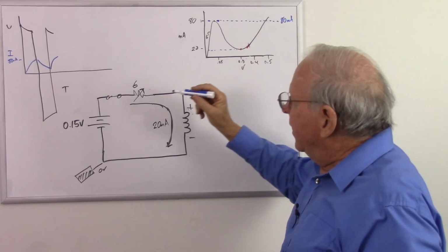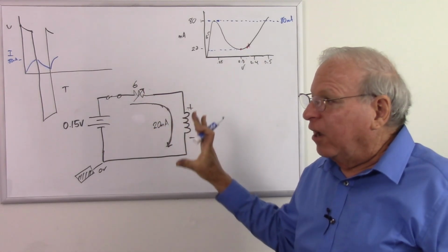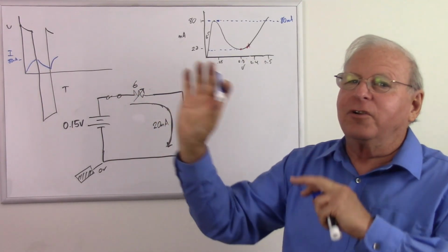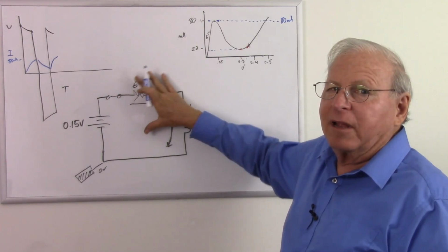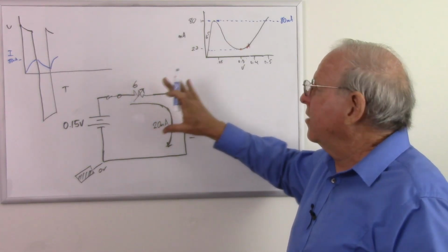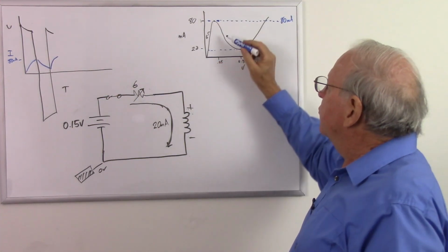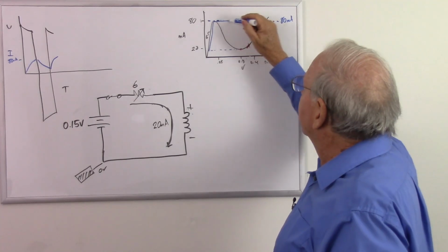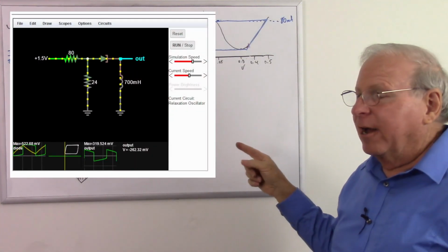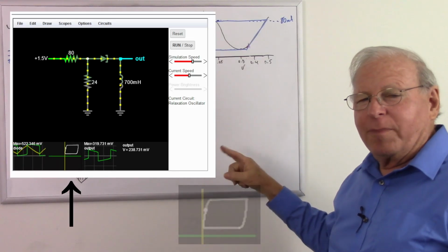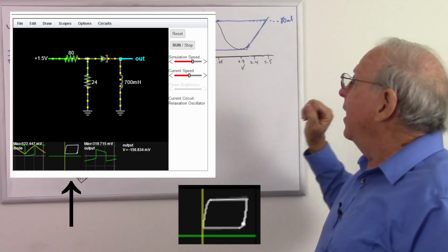And so what we find is that as this tunnel diode keeps adjusting its resistance, just following all these principles we've been learning for all this time, it has to keep changing its impedance from about 6 ohms to about 600 ohms, then relaxes that, allowing this curve to happen. Then it has to jump back down to 6 ohms. So we get this hysteresis loop here. And that's what's in the simulation. You can see at the bottom, it's showing the hysteresis loop happening on the voltage versus current on the scale down below the circuit up higher.